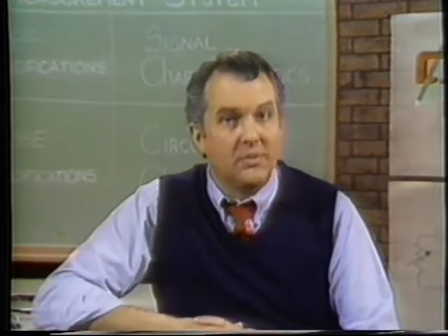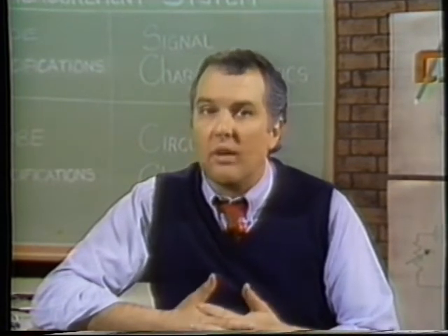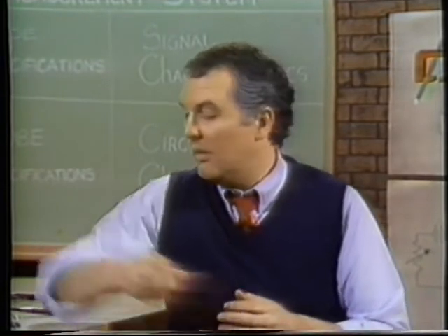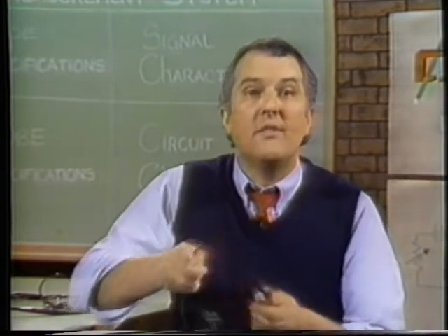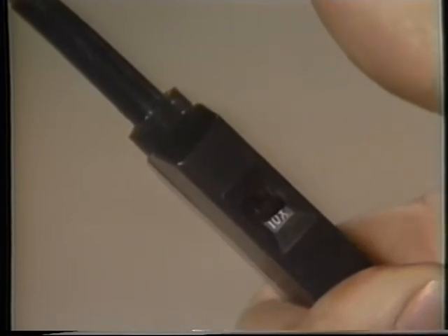Attenuating passive probes are much more versatile. As I said, there are two major families: high impedance or high Z probes and low impedance or low Z probes. Some passive probes are even dual purpose with both 1x and 10x attenuation settings.